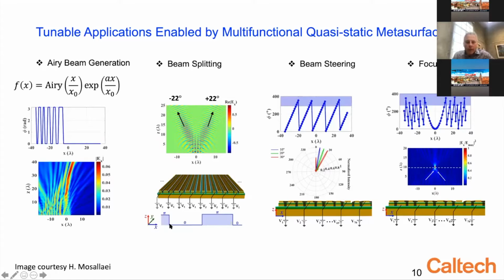Here we have phase that alternates between arrays of antenna elements in a periodic array between 0 and pi. Or I could, for example, array the elements in terms of a phase gradient that is approximately linear as I go across the array of discrete elements in a repeating fashion, which would allow beam steering at a well-defined angle determined by the phase gradient. Or, for example, I could design a parabolic phase profile or some other phase profile which is matched so as to be able to produce a focused beam in front of or behind the aperture.